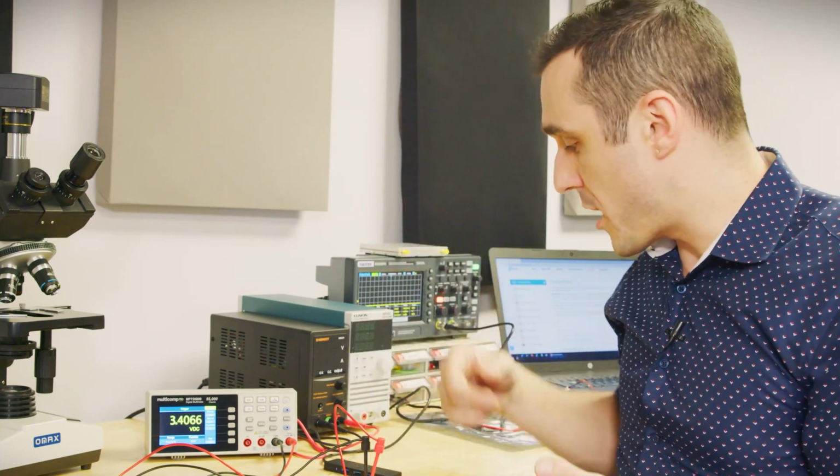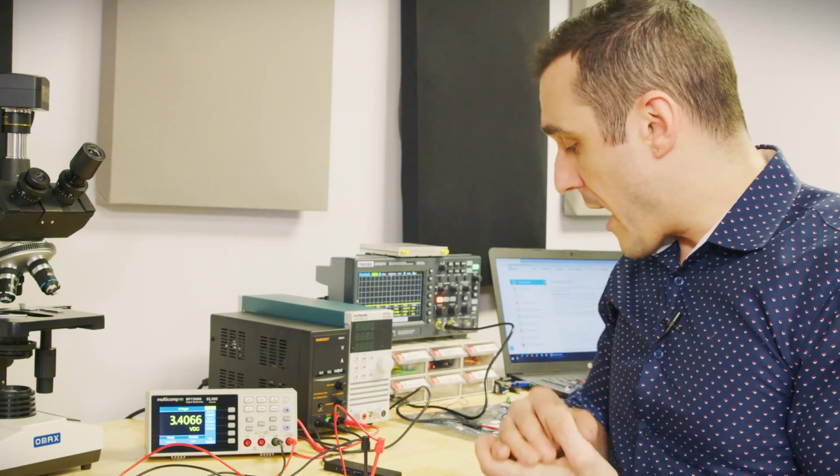So we've got a few design requirements here, okay? We have to take in 5 volts and data over a USB connector. We have to then output 5 volts through that same bus voltage, as well as 3v3 coming from the CP2102. And then we have to output RX and TX.